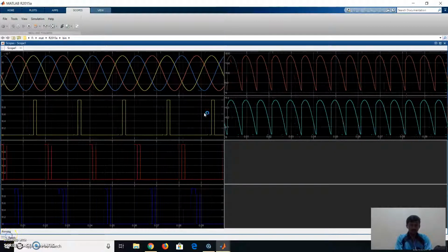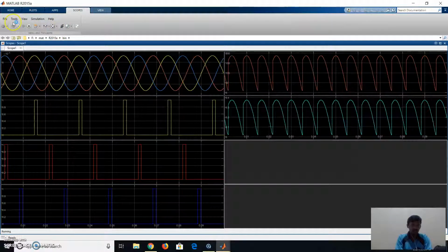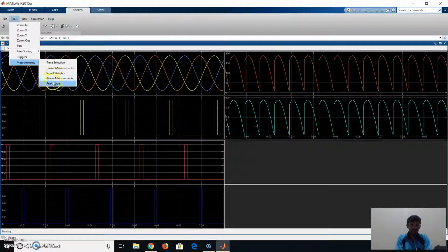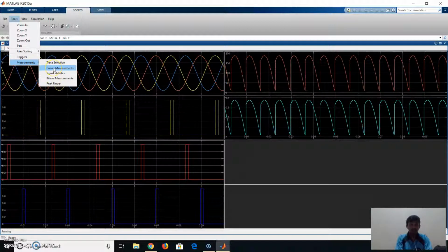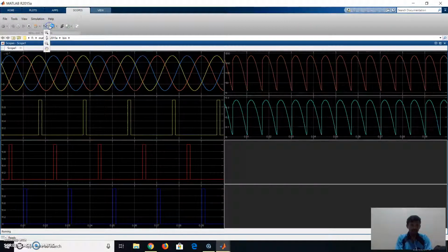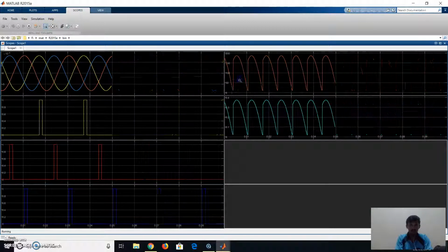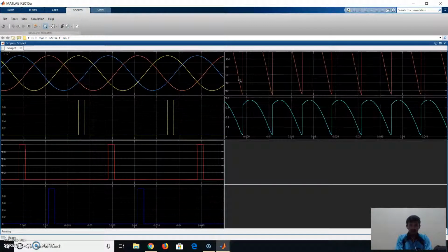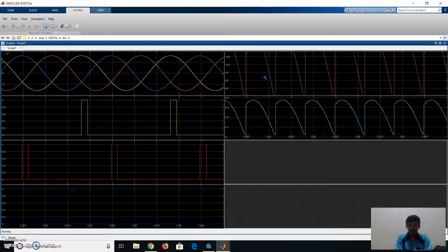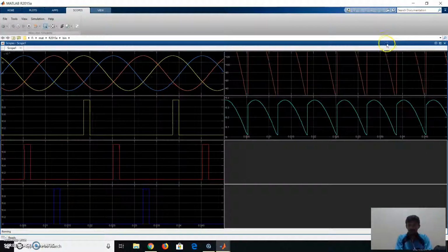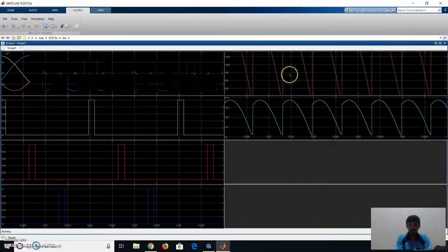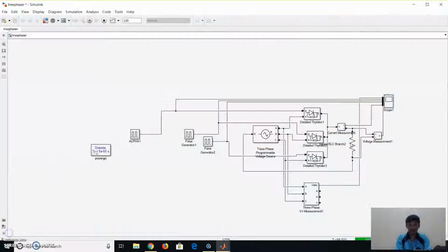So also measure all this input voltage source in the tool. Include the measure and click on the measure. Here the peak finder, signal, and cursor measurement. You can choose cursor measurement and search. After this, we can zoom this waveform and see how the firing angle alpha is changed. So double click on this window.